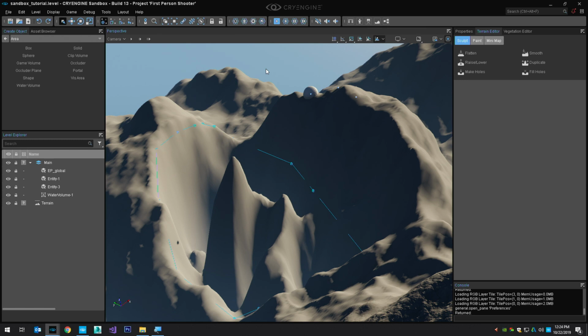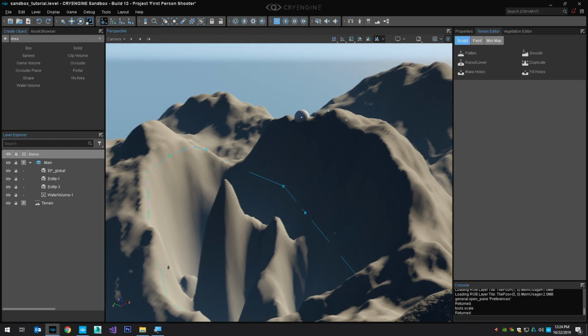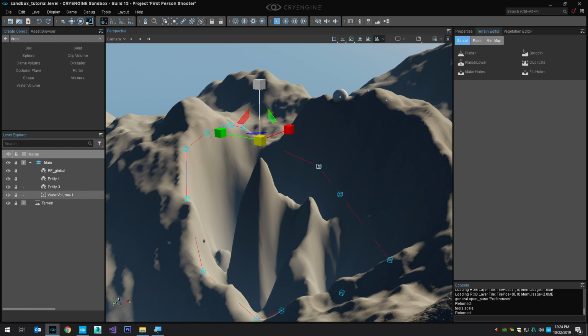So I'm going to use my scaling tool, which is here, the 3 key, this gizmo here. And I've got the entity selected. And I'm just going to grab this box, which is scaling vertically, and drag down, down, down, down. I may need to do it 2 or 3 times. And all of those points, the height of the points is all going to equalize like this. You see what it's doing? I'm reducing the distance over which the points are distributed on the vertical axis.